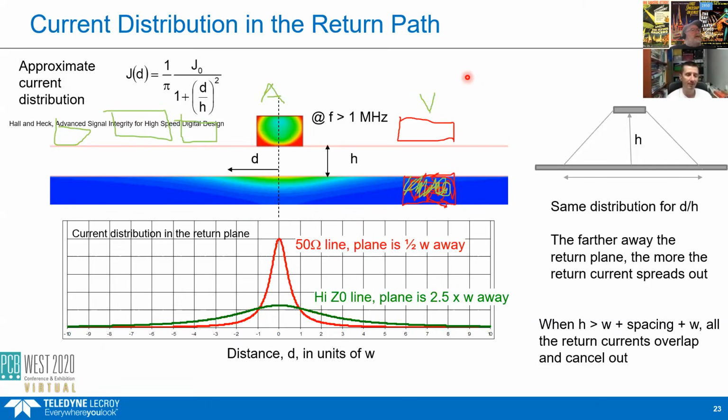Well, let's see. When you're electrically short, depending on the impedance of the two lines, that will determine whether it's dominated by capacitive coupling or inductive coupling. If it's either one, generally, the longer you make it, the larger that coupling will be, if it's electrically short. If it's electrically long, then the near end crosstalk saturates, but the far end will continue to increase. Okay, I didn't know that.